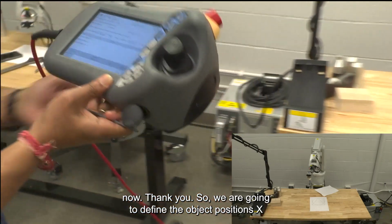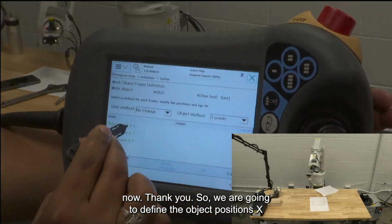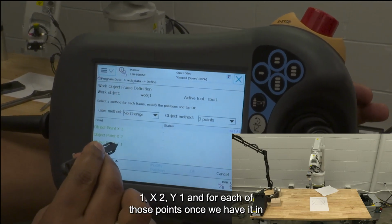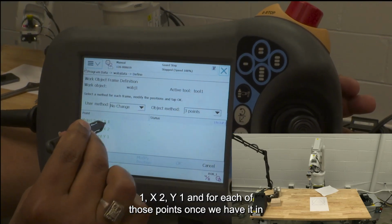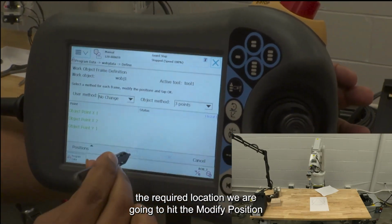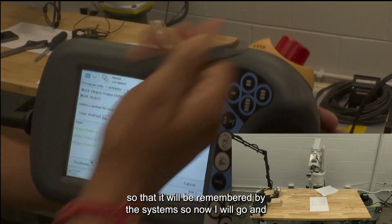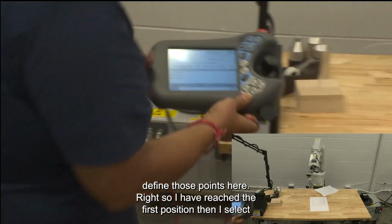So, we are going to define the object positions x1, x2, y1, and for each of those points, once we have it in the required location, we are going to hit the modify position, so that it will be remembered by the system. So, now I will go and define those points here.